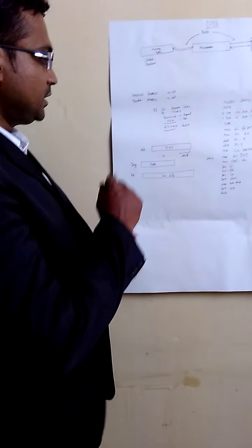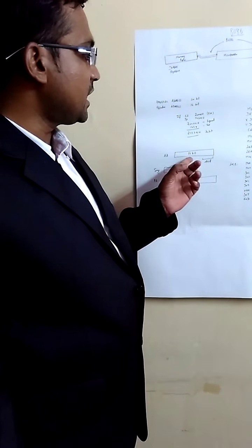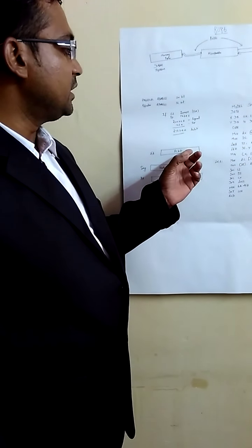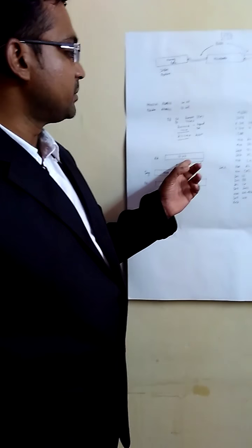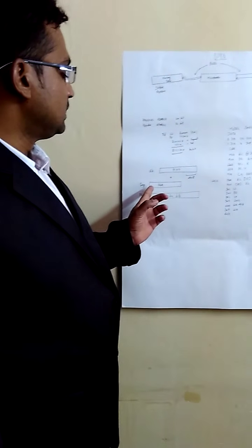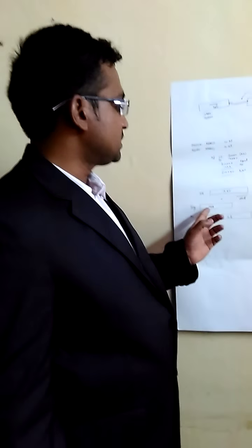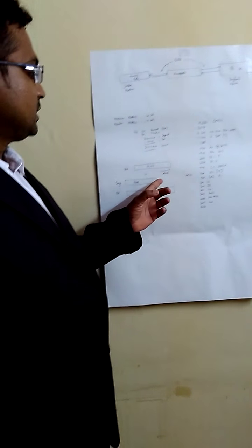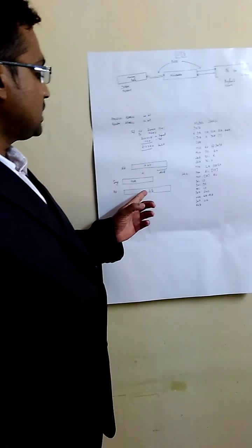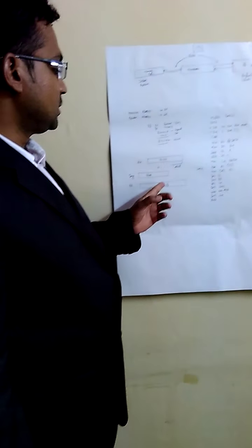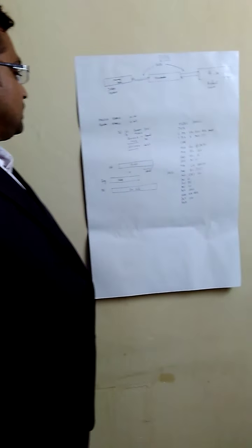So the block diagram here shows the address calculation method. The first one is the effective address, which is derived from any of the 4 segment registers, and the next one is IP, the instruction pointer, 16-bit. If we shift towards the left hand side, we can get the 20-bit address. The 20-bit address is called the physical address.